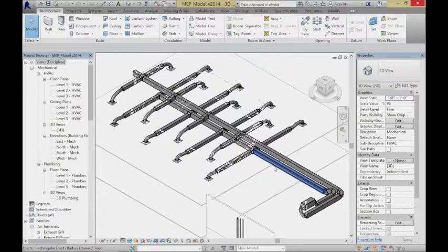One thing we do is figure out where we want all the return locations and the diffusers that are going to supply air, and the ones that are going to pull air away. We can figure out how many of those we need in each room just based on the volume we have to move. So that part's pretty easy. I'm going to go scattering them around.